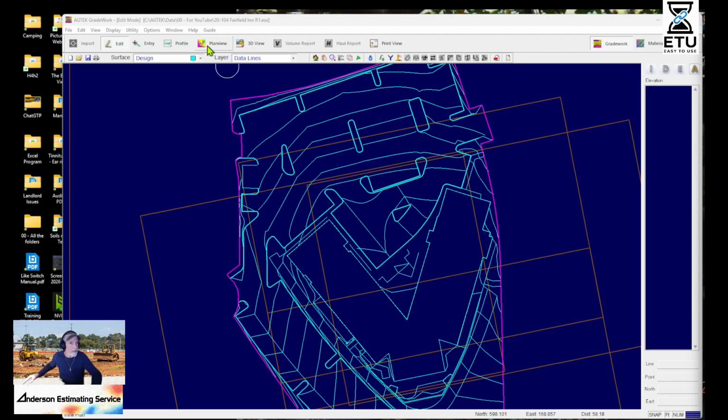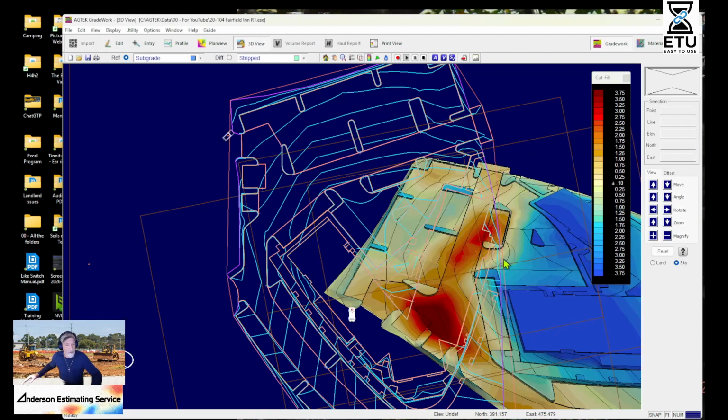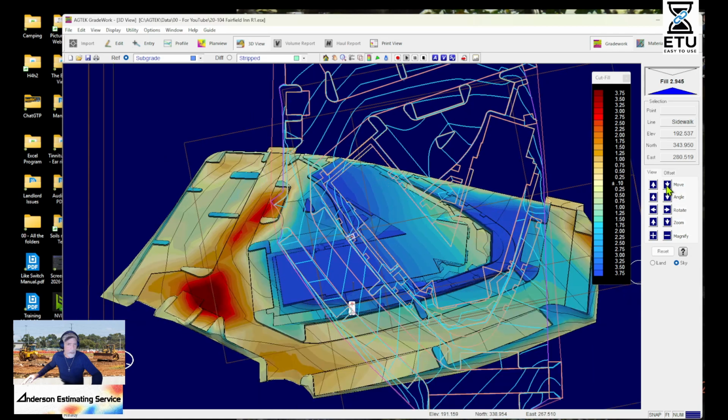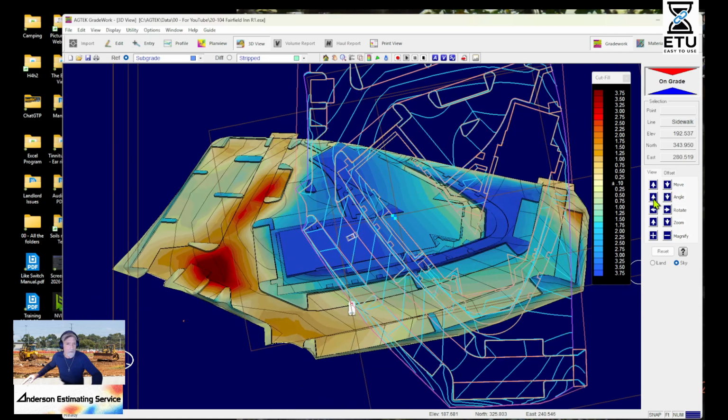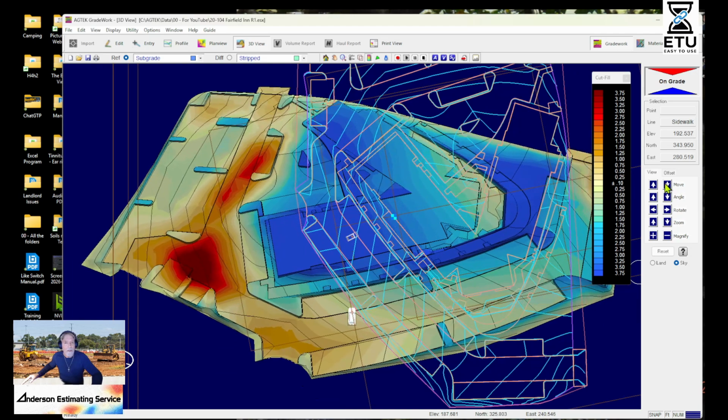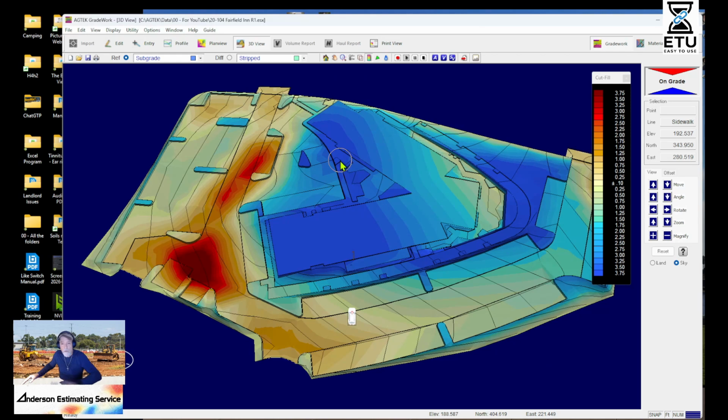That's your quantities. And then you apply your shrinkage values and all that stuff. Now that's contractor specific. I can go through calculations with you on that. There's all kinds of different ways to actually mathematically calculate your shrinkage. And then you should be looking at your soils report for all the strip losses and stuff like that. So those are very important. So this is what you should compare when you're doing your takeoffs, okay?